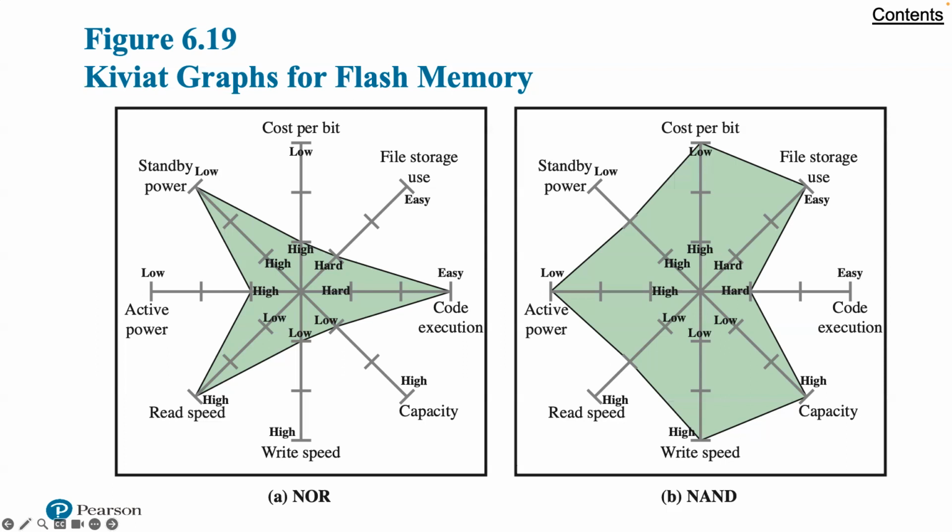For internal memory in an embedded system, NOR flash memory has traditionally been preferred. NAND memories have been making some inroads, but NOR remains the dominant technology for internal memory. It is ideally suited for microcontrollers, where the amount of program code is relatively small and a certain amount of application data does not vary. For example, the flash memory in figure 1.16 is NOR memory. So you can go back to chapter 1 to review that figure if you'd like.